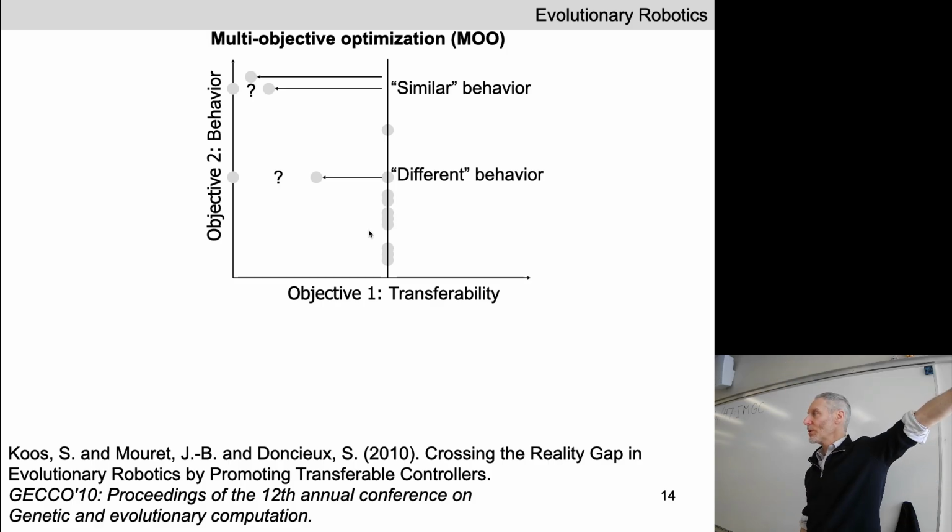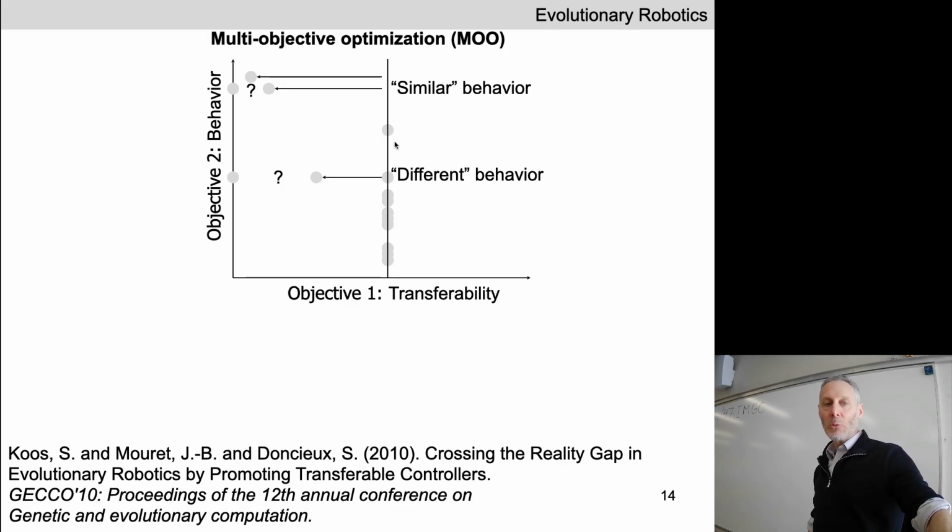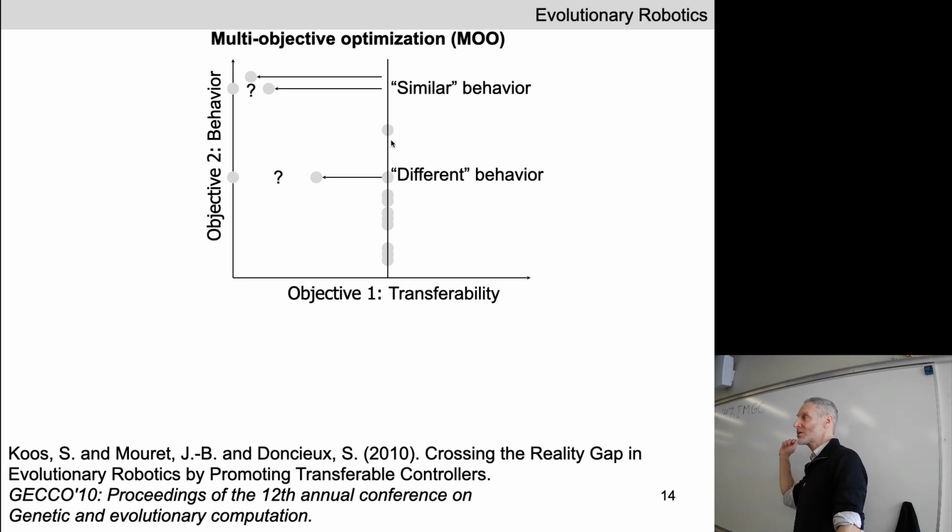We go to the supercomputer, we grab a point off the Pareto front, a controller that is efficacious in simulation and is estimated to have high transferability, send it to the real robot. And as the real robot starts to be controlled by that controller, we just keep running the evolutionary algorithm. The real robot takes 30 seconds or a minute to run that controller. We get back those 3 behavioral features. The real robot puts up its arm again and says, I'm ready for another controller.